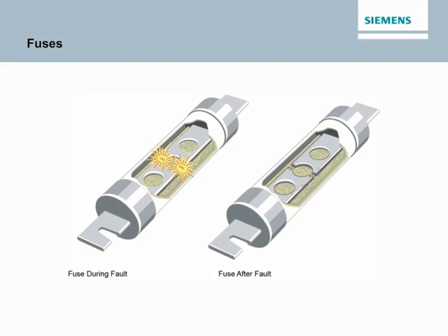Non-time delay fuses provide excellent short-circuit protection. When an overcurrent occurs, heat builds up rapidly in the fuse. Non-time delay fuses usually hold 500% of their rating for approximately 1/4 second, after which the current-carrying element melts. This means that these fuses cannot be used in motor circuits, which often have inrush currents greater than 500%. Time delay fuses provide overload and short circuit protection. Time delay fuses usually allow 5 times the rated current for up to 10 seconds to allow motors to start.